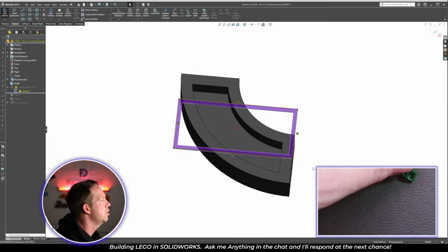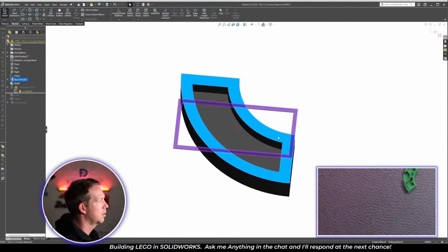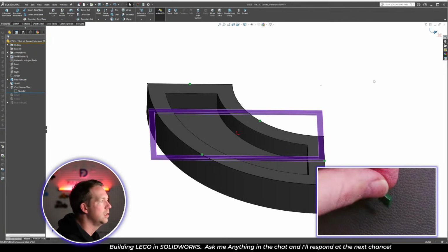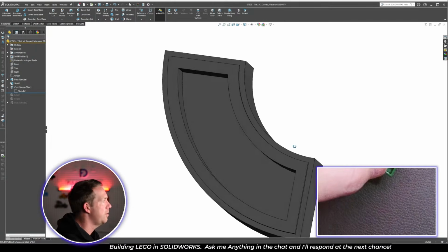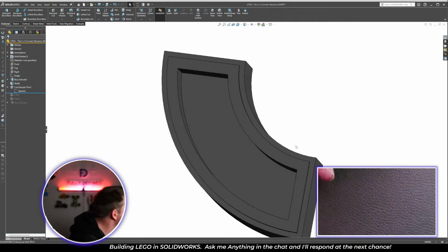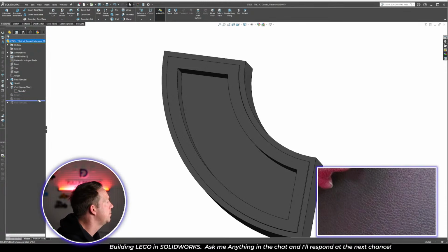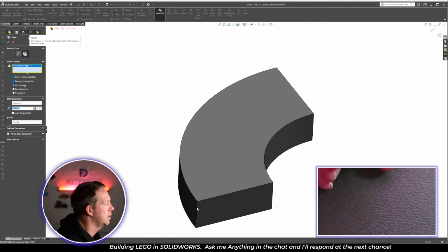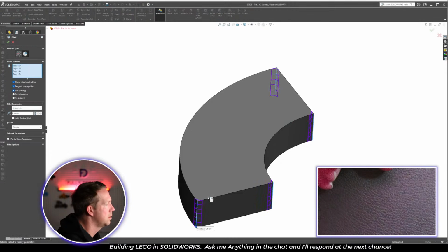But this is a cut extrude thin, cutting away material from the outside edge that we've converted to get that kind of lip shape around it. So that's pretty good. It's got a couple of fillets on it. I think they're going to get some errors. We have, it's going to be the 4 edges.